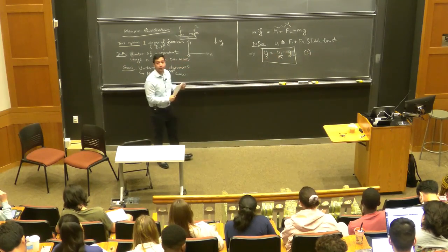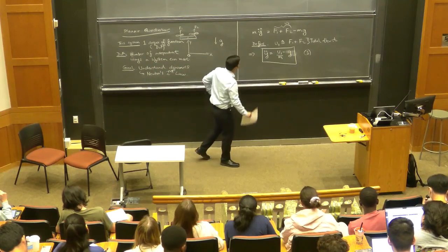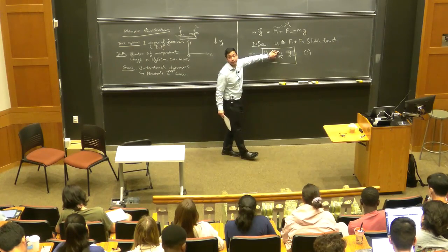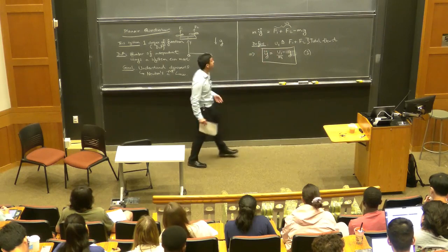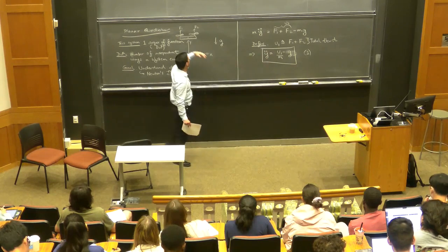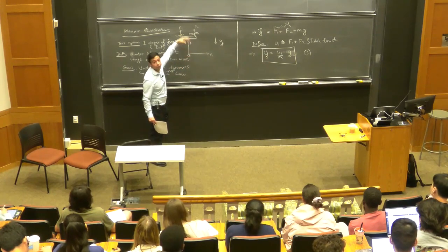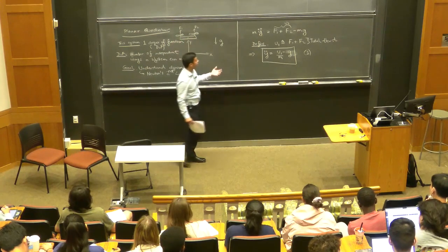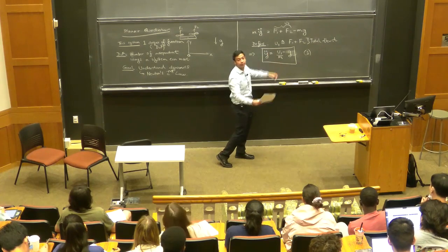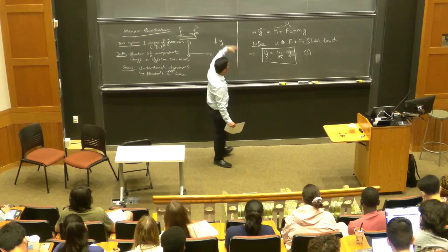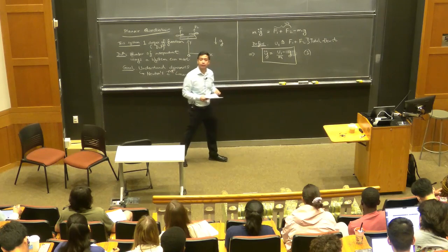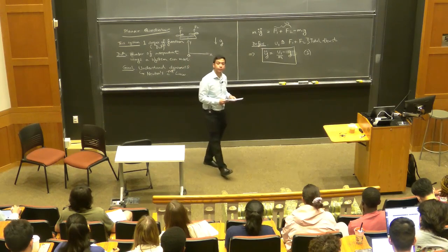So this is a differential equation, and this basically tells us how the system is going to behave. If I prescribe a particular value for U1, so a particular total thrust that the propellers are applying, and if I give you some initial conditions, so if I tell you what height the drone starts off at, and what speed, so what y dot it starts off at, you can, at least in principle, integrate this differential equation forwards in time, and that will tell you exactly what height the robot will be at any given time. All right, any questions on this so far? Okay, good.